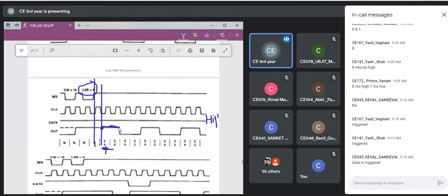Okay, so if it is becoming 0, then it will say, okay, now I have to reload the count. So the count is reloaded and it will make your out 0 for the new count, because it will alter the polarity of out. Again it will decrement it by 2, continuing with the previous polarity of out. Now the count is 0, so alter the polarity of out and reload the count. What is the count? It is 4. So keep it, and decrement it by 2. Is it 0? No. Then keep it high.